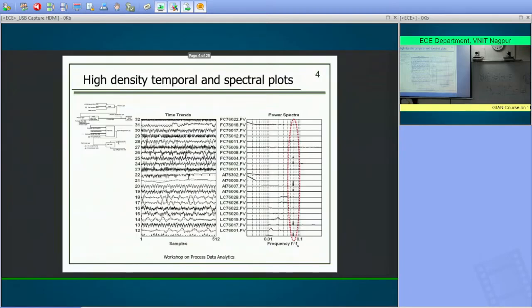Typically, in a refinery, you have multiple processes that are interconnected, right? You have upstream processes, downstream processes. If there are oscillations in an upstream process, those oscillations tend to propagate through the downstream processes as well. And that's what we're seeing. Now, just by looking at this graph, you can't tell where the problem is, where the oscillations originated, right?